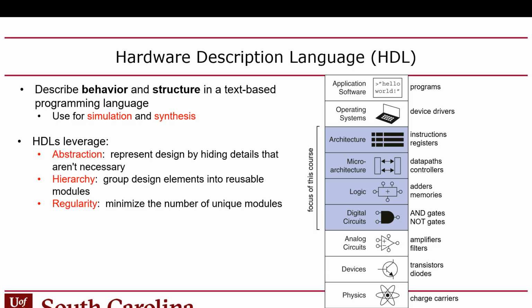Who could design that? Well, they only design one core and then they stamp out 1,500 of them. So it's very easy to design a GPU because they only have to spend time designing 1/1500th of the die, and then the rest of it is copied and pasted, right? That's why GPUs tend to be very scalable in that way.